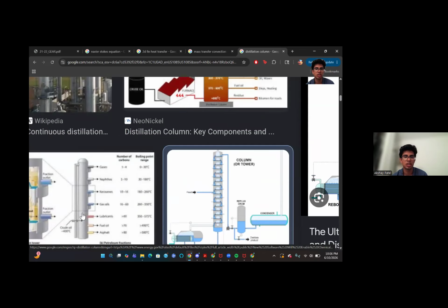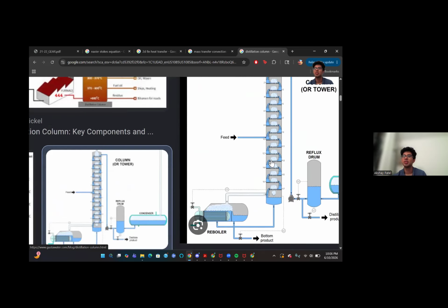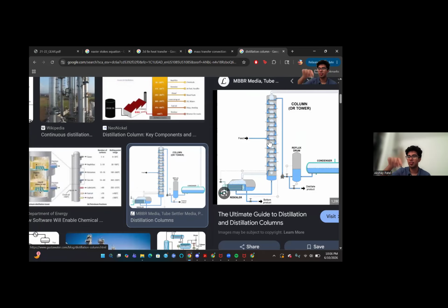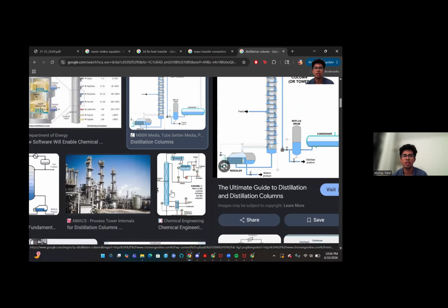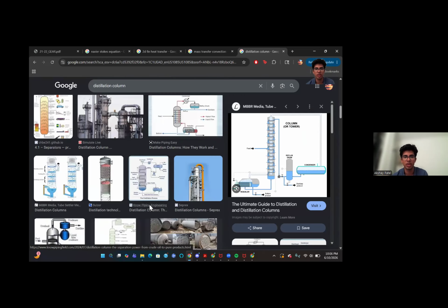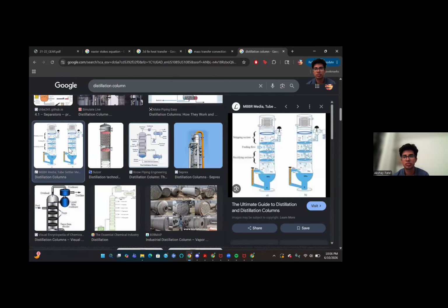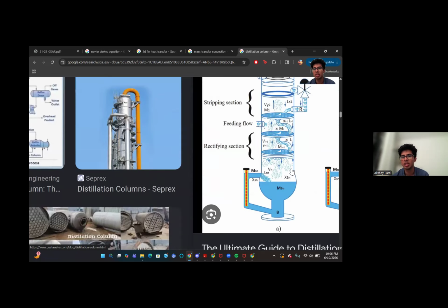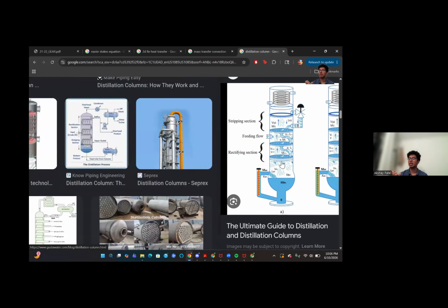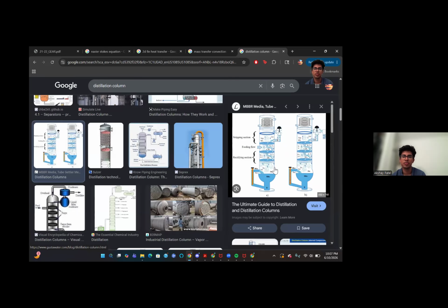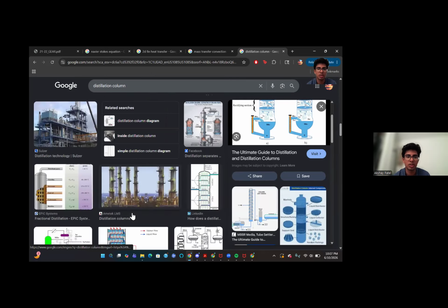So there are equations that go along with the different phase transfers that happen between the trays, and you can basically model that. There are phase diagrams that you can step between to figure out the different purities that get involved with the different number of trays. Yeah, you basically have to balance everything out. You have to figure out this much mass is going up, this much mass is going down, and then use those variables in the equations to figure it out.